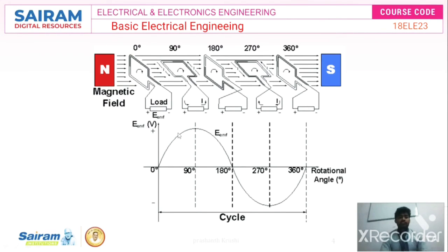And next we have another conductor, another rotation. This is only one conductor, okay, keep it in your mind, just one complete rotation, like one circle rotation. At 180 degrees it comes, definitely 0, and again at 90 degrees, so negative here, more induced EMF in the negative half of the cycle, and at 360 again parallel to the field, again 0. So this is one complete cycle, right? So this is the generation of AC voltage.